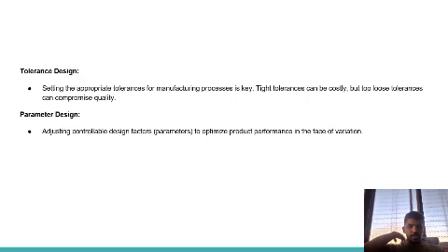Key principles of robust design. First, tolerance design. What is tolerance? As mechanical engineers, we all know what tolerance is. So how does tolerance work in design? Setting the appropriate tolerance for the manufacturing process is key. Tight tolerances can be costly, but too loose tolerances can compromise quality.